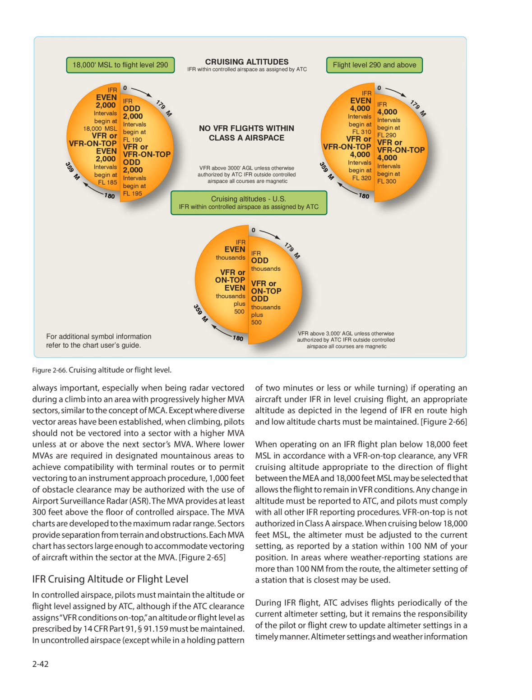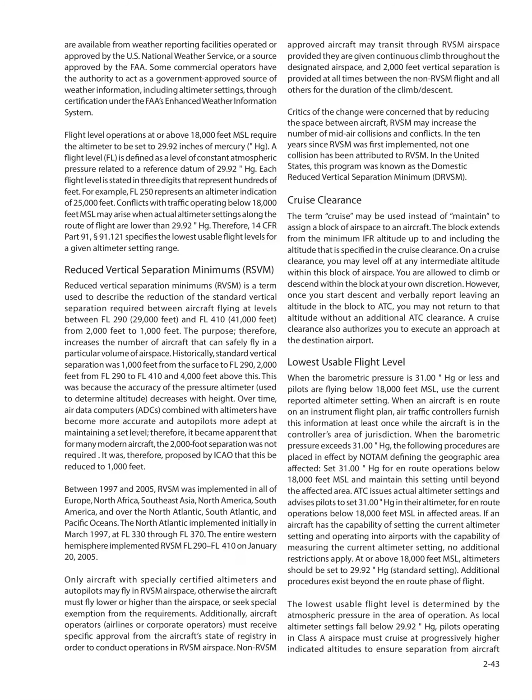Altimeter settings and weather information are available from weather reporting facilities operated or approved by the U.S. National Weather Service, or a source approved by the FAA. Some commercial operators have the authority to act as a government-approved source of weather information, including altimeter settings, through certification under the FAA's Enhanced Weather Information System.